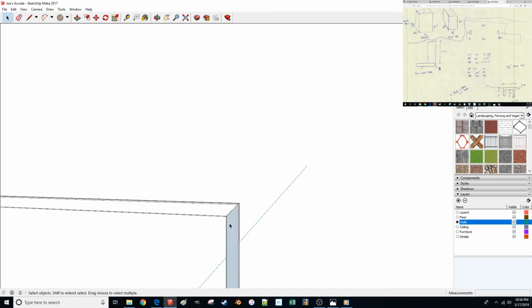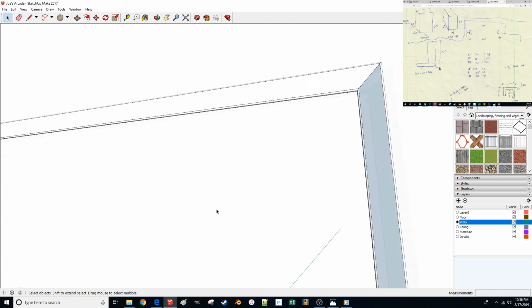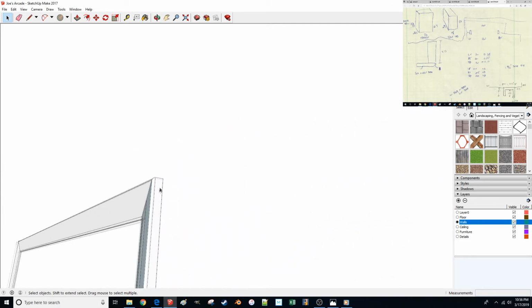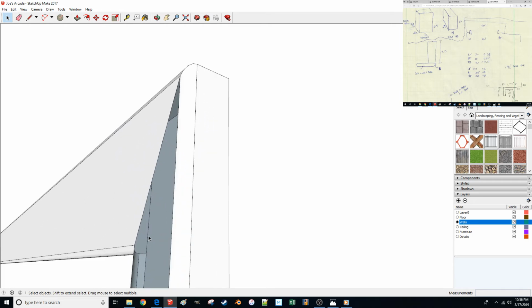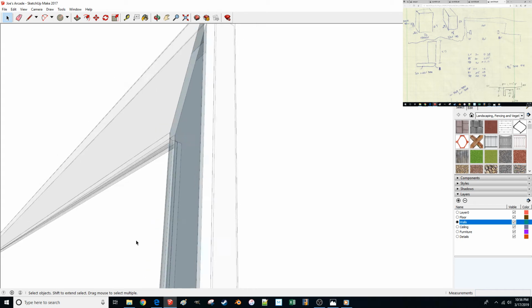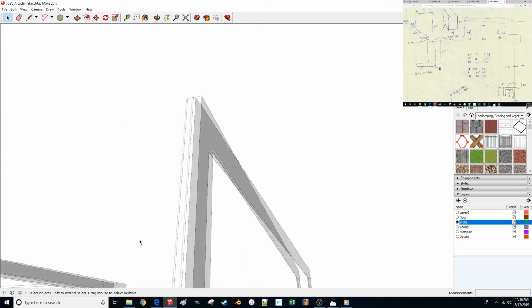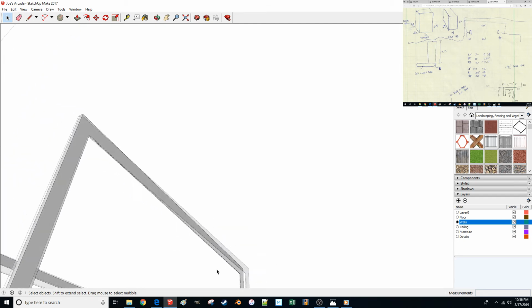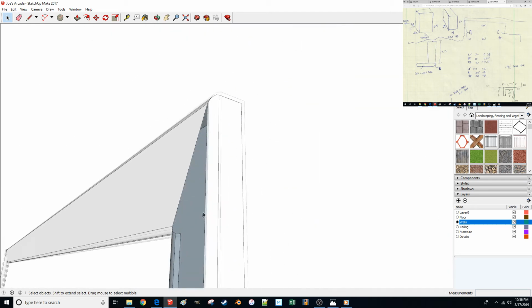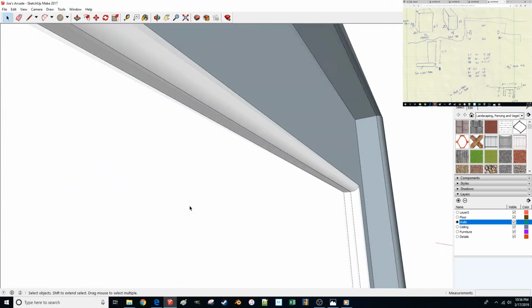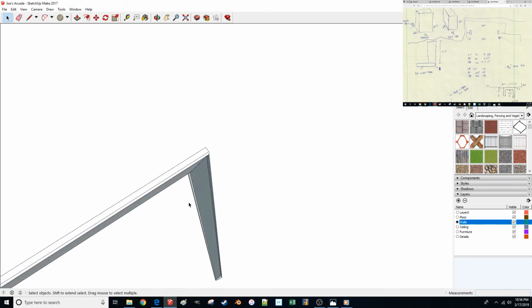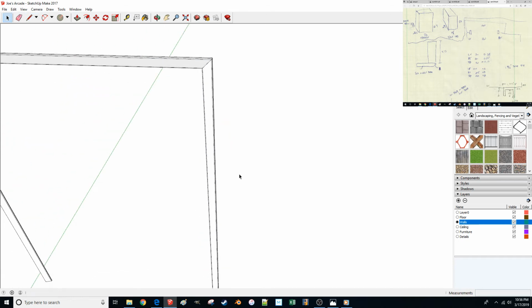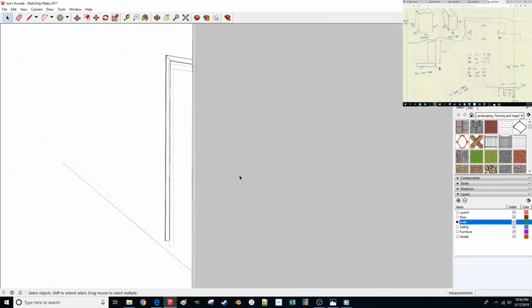A little bit touchy here. I'm going to zoom my camera in a little bit to make it a little easier to control. I am using a 3D mouse for this modeling. It's really helpful for some of this fine detail stuff. Don't have any straight lines on the back here like we do over here, so that tells me I've got that model cleaned up on the inside as well. Just take one last check. I'll get rid of this face for a second and just make sure everything's good and then undo that. There we go. I'll bring that face back. So now I've got that side done.